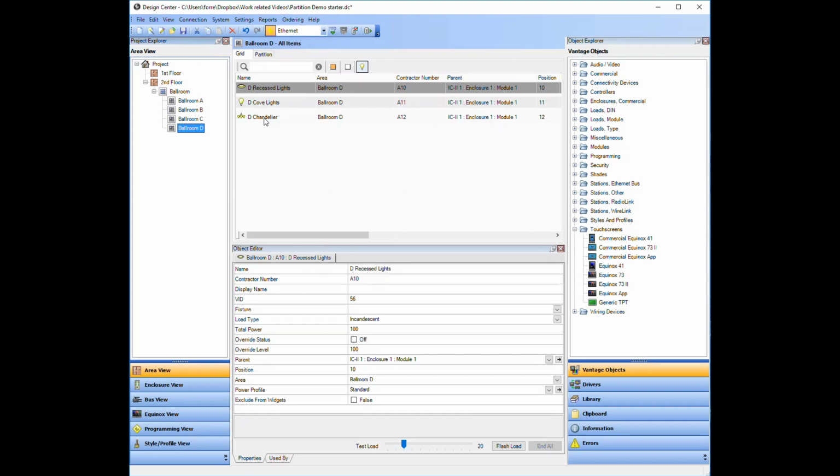So consider how we anticipate a button within a partition room to operate. Let's say we have a button designed to operate the cove lights. This button will always operate the cove lights in the room the button is located, and we will also operate in a synchronized fashion the cove lights in any other partition room in the partition area, provided the partition walls are open to those rooms. But the button will not operate the cove lights in any partition room that is closed off from this location by partition walls, allowing for independent lighting in those areas.